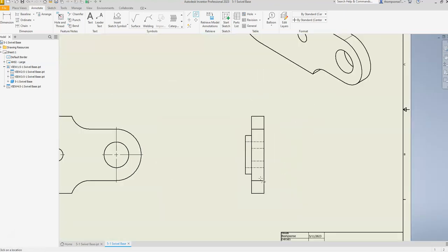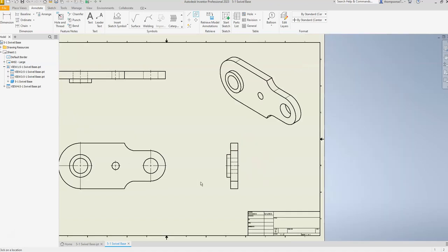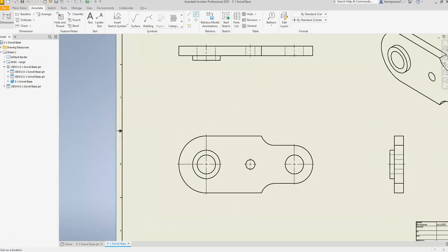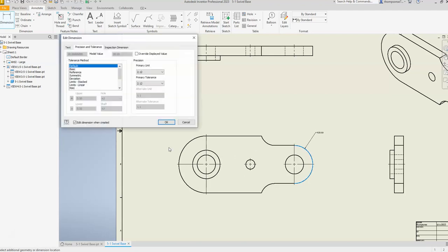And then we'll come over and do these, and they're kind of all the same. So choose those. You're only going to have really one bisector. Just make sure you extend it through both parts of the part. All right, so now we can start our dimensions. And we'll start with my outer circular features.